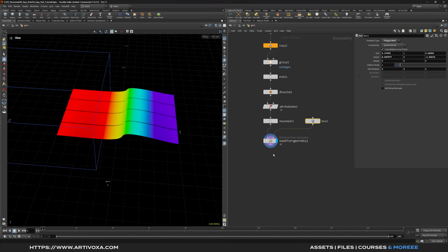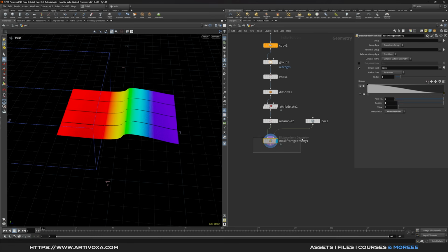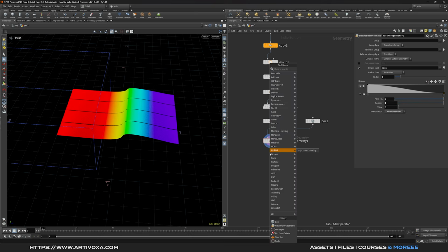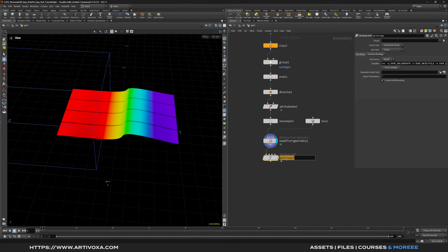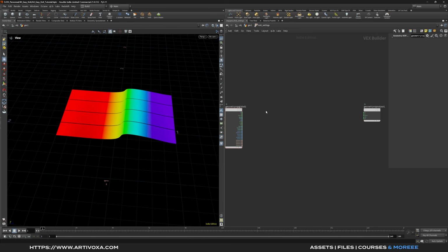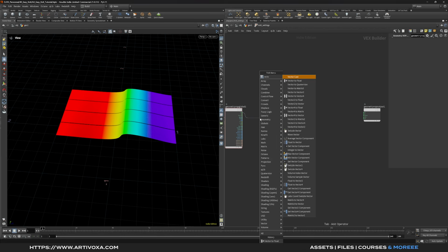So now let's create the strands shape and strands deformations based on our mask and our fall-off attributes. To do that, you can use a point VOP. Here you can rename it something like knit settings, and here you can dive inside. So the first step is to split these position vectors into 3 different floats. To do that, let's use the vector to float node.